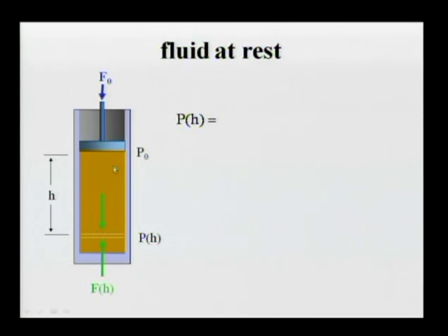Well, so we have to figure out what are the forces exerted on this part of the fluid above the slice, because the slice supports the fluid. Can you see it? All right, so there is a force exerted by the piston, and also that fluid has weight, which means that there is force exerted by the piston, force exerted by the earth, and the third force is exerted by the slice. The force exerted by the slice is opposite to the other two and makes it behave like it does.